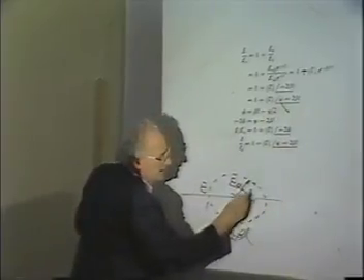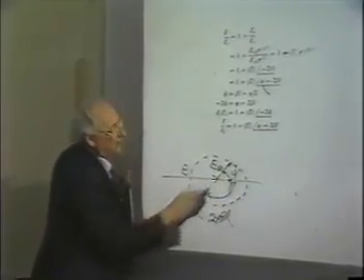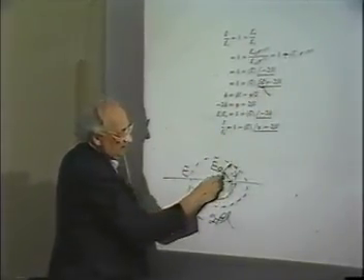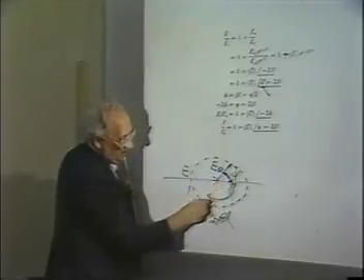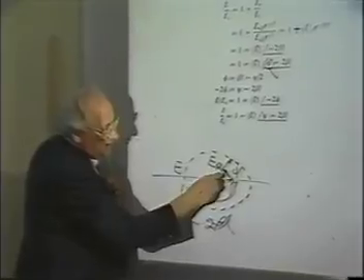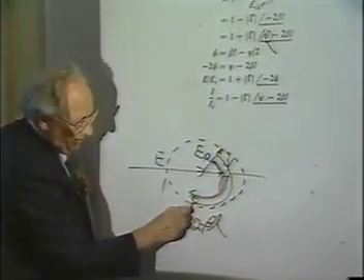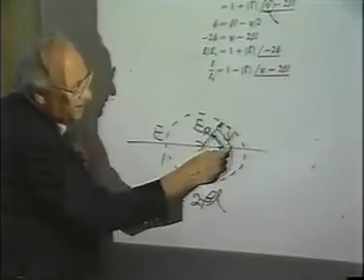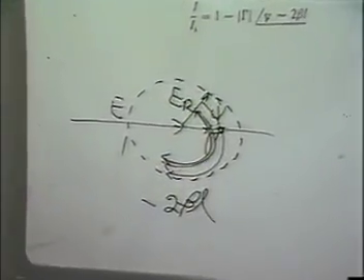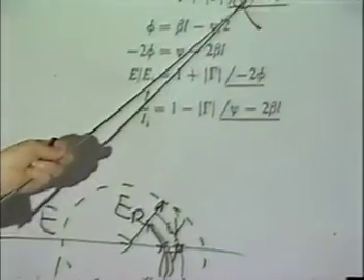It's very easy. See this angle here between right here and here? That's this angle here. Okay? Now what's this angle here? 2 beta L. Notice, 2 beta L is all the way from here over to here, right? If I subtract this one from it, all it does is put me right here at this axis, the Z maximum axis. That's all that equation tells you, is that this is starting from the Z maximum axis.